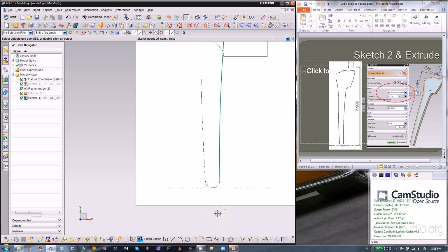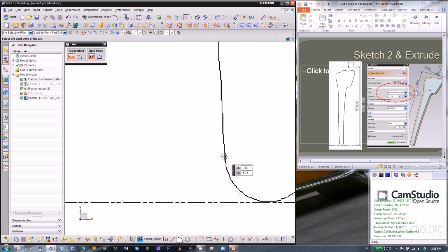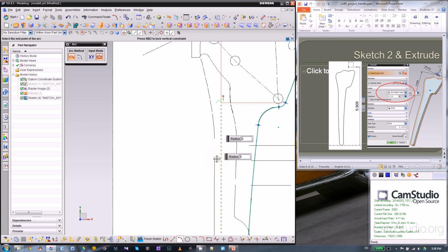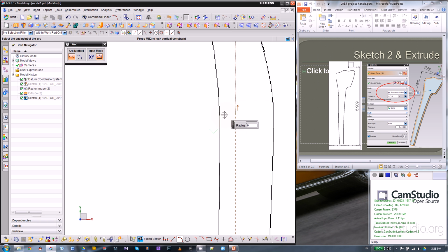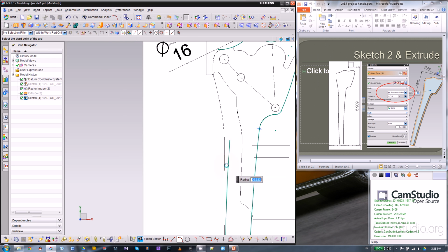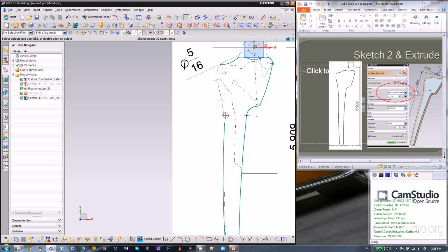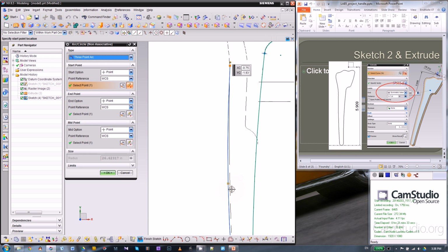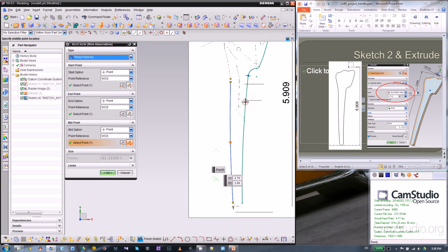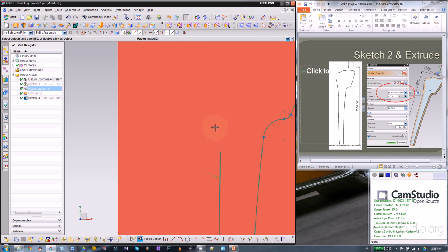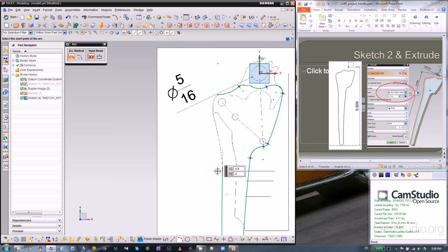And we can leave this section alone, go for the other big long arc. So it ends about here. Still we have the vertical constraint pulling us away. So drop the arc first, close the command, and move this to the proper location. You can also adjust curve. Okay, and I leave it here just for another fillet between this and